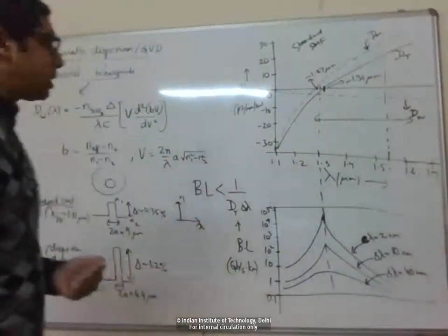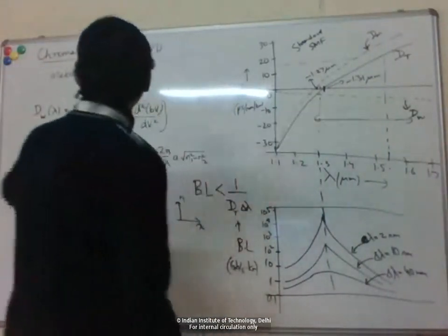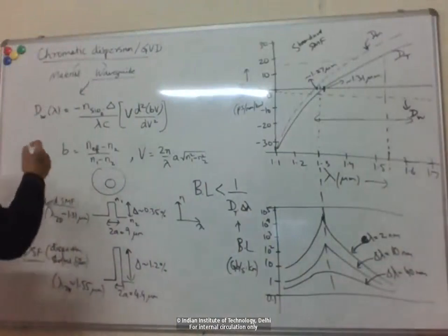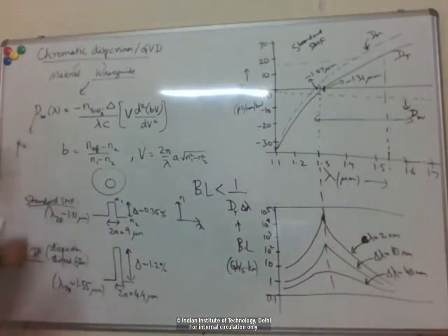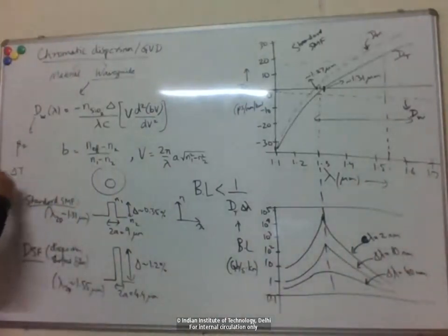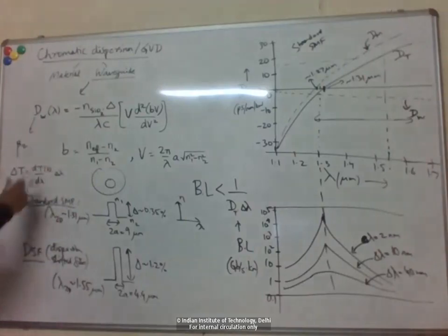Basically, recall this D was nothing but the second derivative. Or equivalently, remember there was this quantity beta 2, which is basically just D scaled in different units. That was the second derivative of the propagation constant with respect to frequency. We did this by saying the pulse spreading was the propagation time as a function of frequency or wavelength, and then we take the derivative with respect to wavelength.